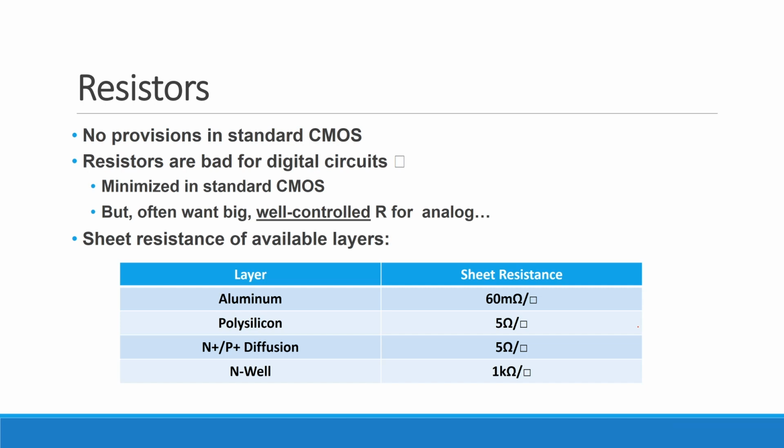And the way to see that is just to look at the so-called sheet resistance of some of the layers. Does everybody know what sheet resistance is? Raise your hand if you don't know what I mean by that. All sheet resistance means here is, if I look at any resistor, the resistance is rho times L over the cross-sectional area, right? Where, if that's the direction of current flow, then that would be the length. Let's say that's the width, and this is the height, okay?